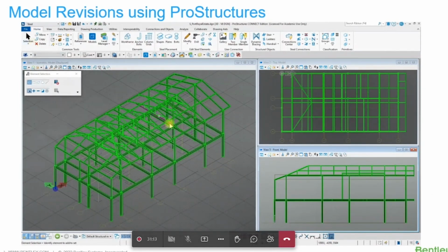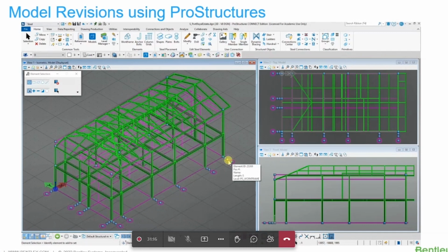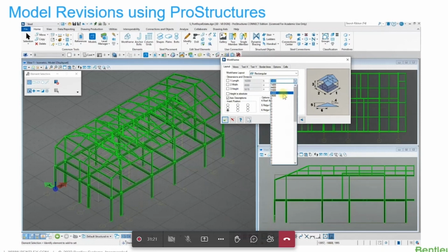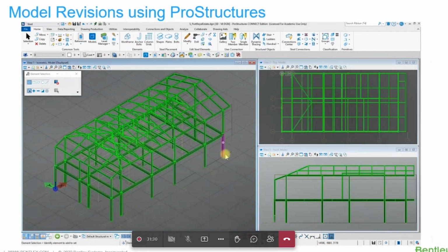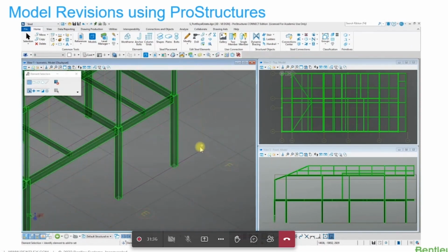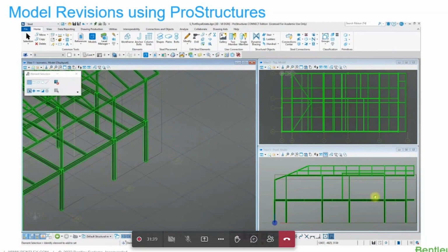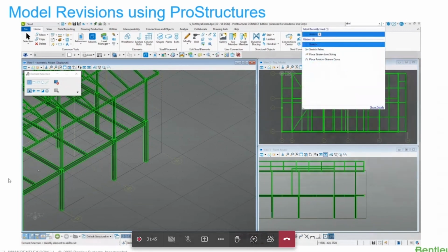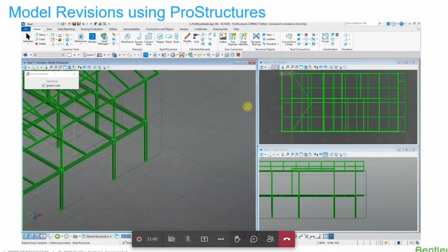And ProStructure po yung ginamit natin. So, regarding revision, very easy lang yung gagawin. Actually, you can just modify the work frame na pinakita po ni Junius kanina. Yan, pwede po kayo mag-add ng additional grid dito sa ating work frame. So, ang major revision po yung nangyari dito sa ating project. So, nagkaroon po ng additional grid line. So, na-extend yung portion dun sa likod ng structure. So, in-extend po yung veranda. So, ginawa dito is naglagay ng additional grid and then in-stretch lang po yung ating structure.